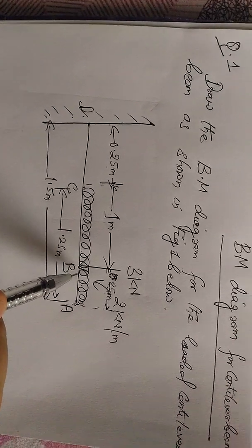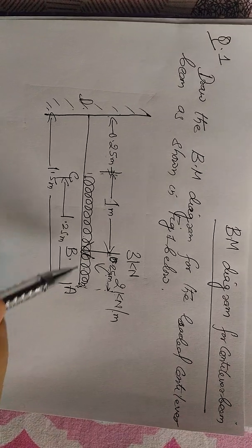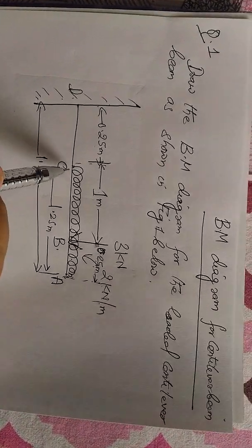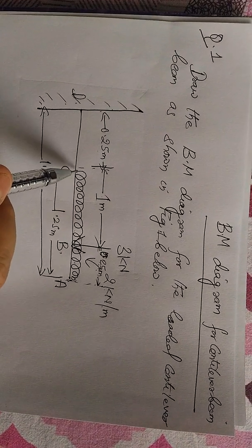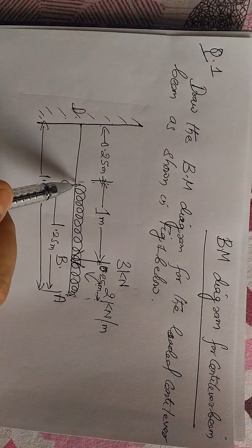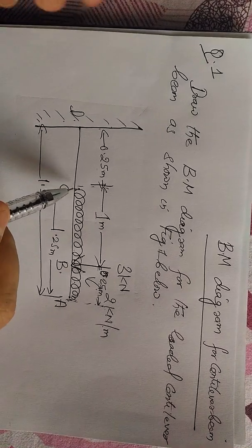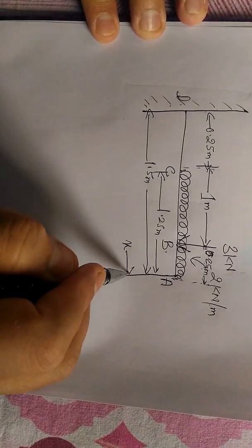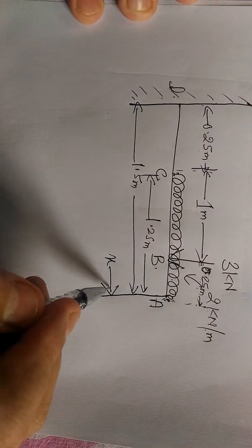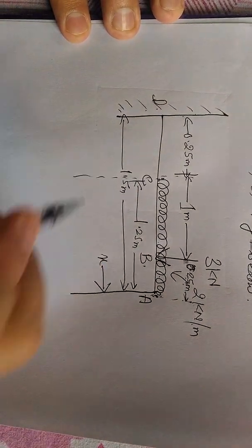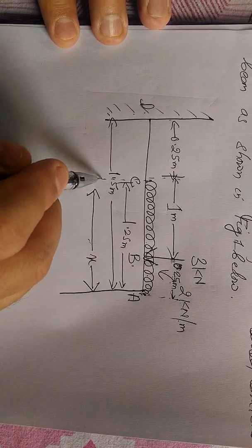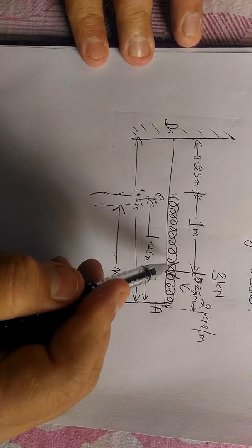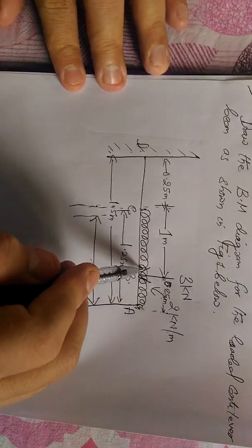in the bending moment diagram you need not worry about point loads. Directly you can take a section starting from the free end till the completion of UDL, as we have done in the question related to the bending moment diagram for simply supported beams. So we'll consider a section starting from the free end of the beam just before the completion of UDL, or the point where the UDL ends. You need not worry about the point loads. If there are any number of point loads in between, that will not matter.